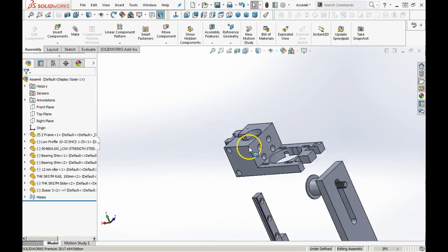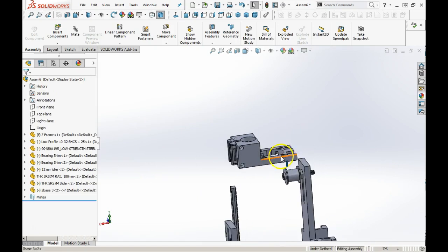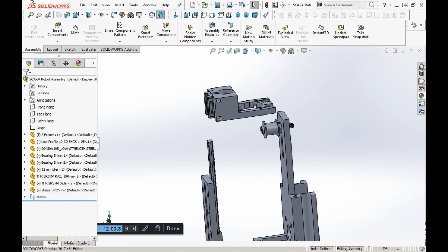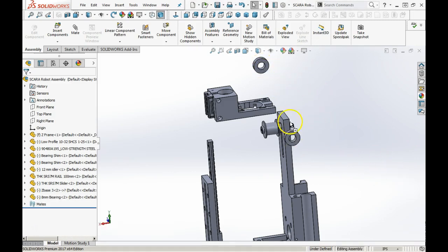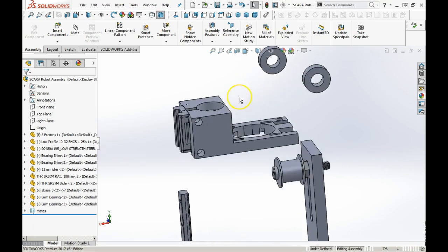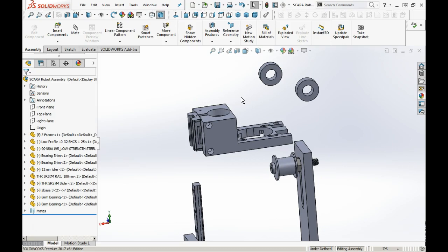And call it good for the mate. And so now we have that block in place. Okay, we're going to bring in a couple of radial bearings. Now, I drew these very simple. You can make them more elaborate with all kinds of ball bearing race faces and stuff. But if we are at this point, we should be able to take these bearings and put them in these